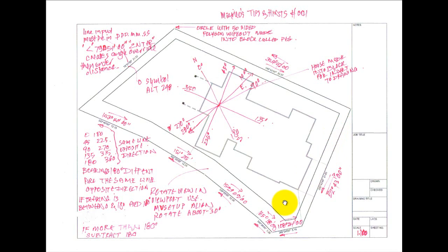You can turn line weights on and off. I suggest you turn it off, it just makes it easier for lining things up. Then I grabbed the block by this corner and made it coincide with where the circle and the offset line met. Then I could delete the circle and the offset line.